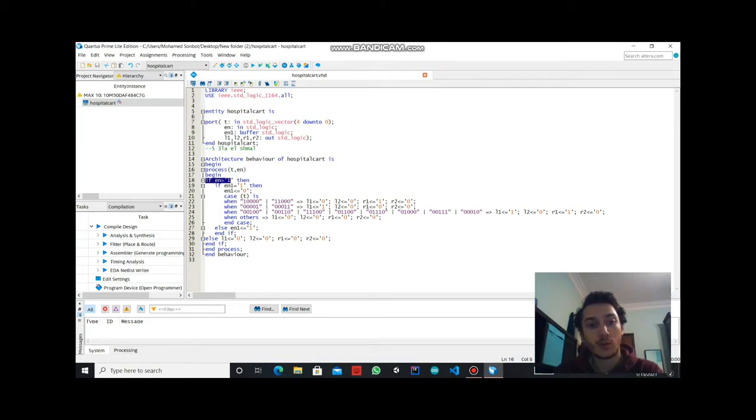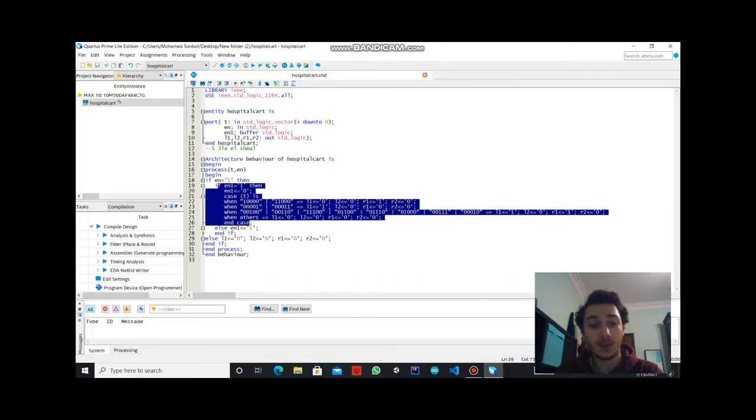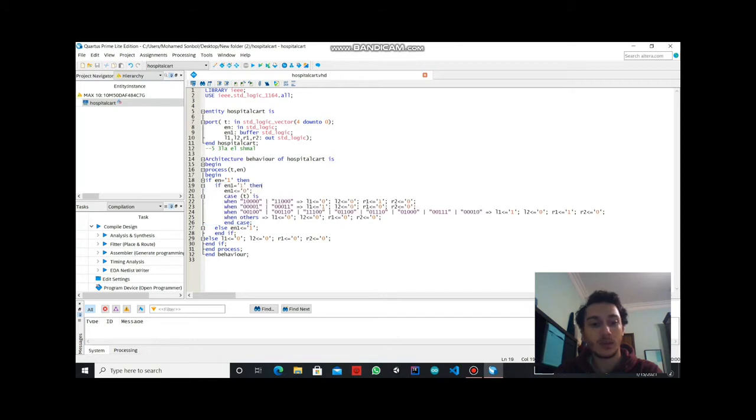First off, we check if our proximity sensor is sensing something or not. If it is sensing something in its vicinity, it sends a 0. If it is not sensing anything, it sends a 1. If it sends a 1, we can move on with our code. If it is sensing something, then we tell the car to stop by setting all of the outputs controlling the driver motor to 0.